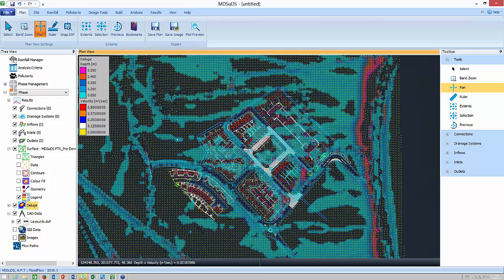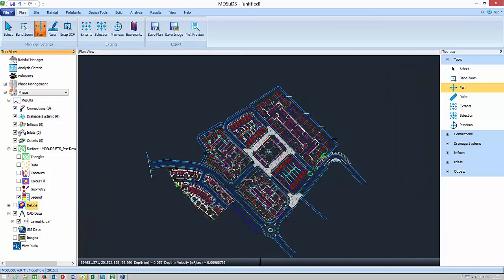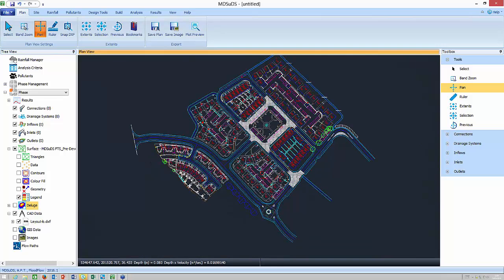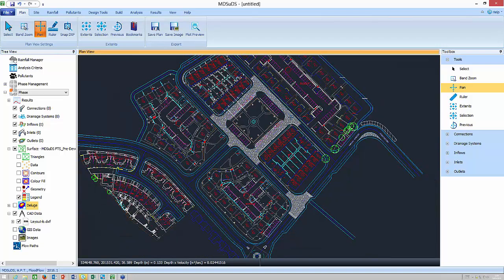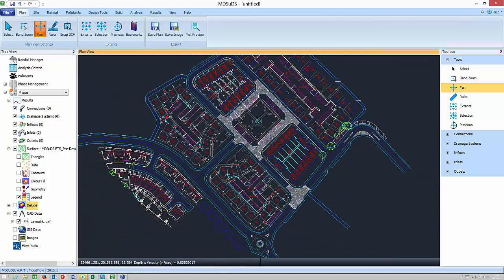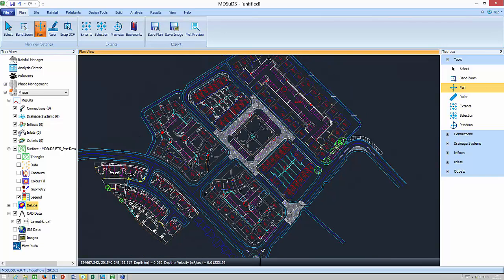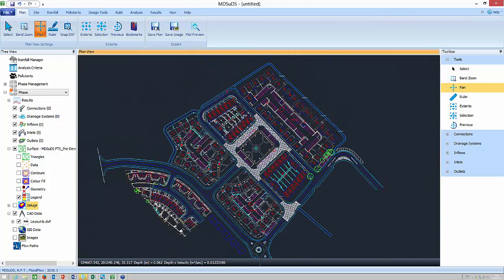And what we could do, if we turn off the deluge, it just switches off the imagery, so I still have the information, but it's switching off the imagery. And let's see, we've got some nice areas here where we could put in some porous car parks by the looks of it. I'm gonna give myself grace and say, oh look, I've got lots of space around here. Of course, I can feel you smiling, because I want to put in some swales around the perimeter.